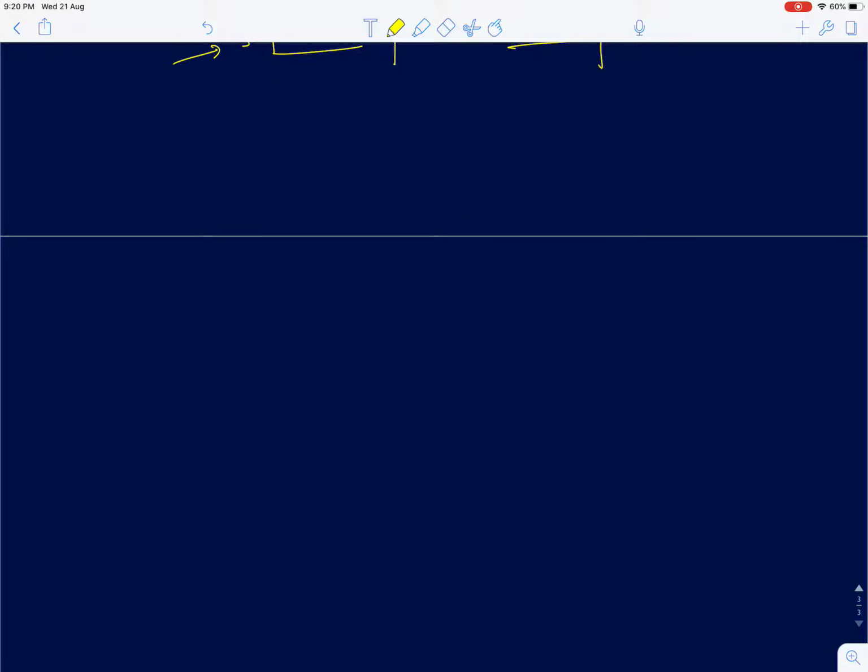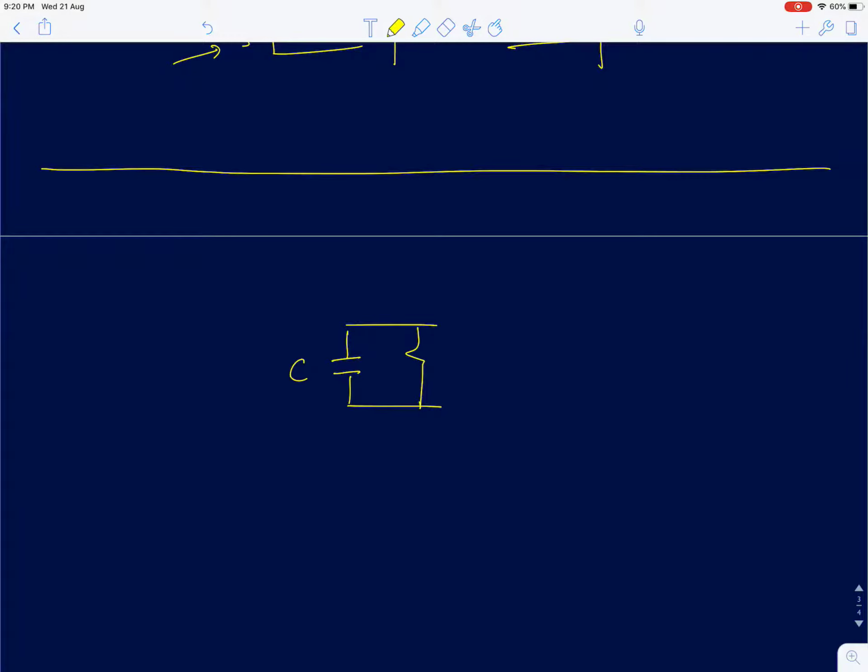The next thing is, similarly we will start with the parallel RC network, wherein we can have a capacitor Cp and Rp. Again, the parallel resistance is also modeled. For example, if you charge a capacitor and leave it open indefinitely, there will be some leakage current across the capacitor which would slowly dissipate the energy. That can be captured by modeling a parallel resistance Rp.